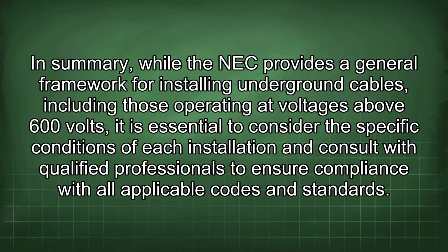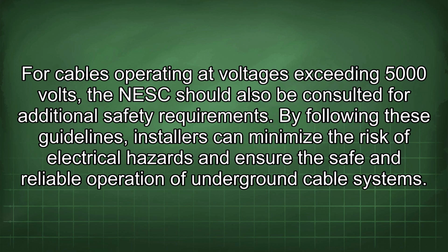In summary, while the NEC provides a general framework for installing underground cables, including those operating at voltages above 600 volts, it is essential to consider the specific conditions of each installation and consult with qualified professionals to ensure compliance with all applicable codes and standards. For cables operating at voltages exceeding 5,000 volts, the NESC should also be consulted for additional safety requirements. By following these guidelines, installers can minimize the risk of electrical hazards and ensure the safe and reliable operation of